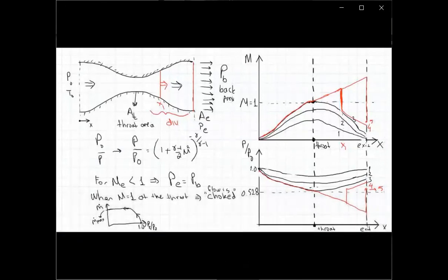So our objective is partly reached, meaning that in the divergent part we do have fully supersonic flow. However, the exit is not supersonic. We also want a supersonic exit, because if you remember our previous video, we discussed, for example, the supersonic wind tunnel condition. In the supersonic test section, we require a uniform constant supersonic stream, which can only be created by placing a converging diverging duct before that. So the duct has to deliver a supersonic exit.